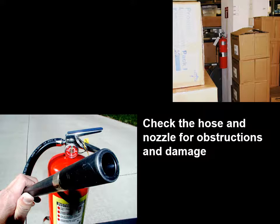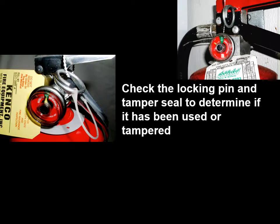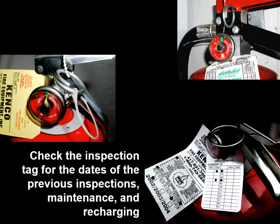The hose and nozzle should be checked for obstructions and physical damage. The extinguisher should be inspected for corrosion and mechanical damage. Determine if the extinguisher is full and if the pressure gauge reading is in operational range. Check the lock pin and tamper seal to determine if it has been used or tampered with. Make sure the operating instructions are legible. Check the inspection tag for the dates of the previous inspection, maintenance, and recharging.